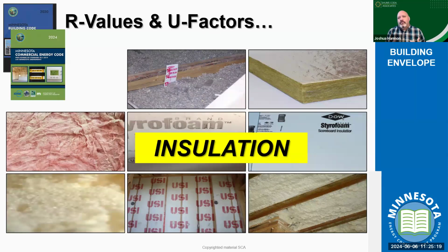If I don't properly designate, and all I see is that I'm putting in a spray foam at R20, and it's not clearly defined in my construction drawings, construction documents, that the system is also providing the air barrier, and the contractor replaces it with an R20 batt insulation, then I'm not going to be able to make sure that project is successful the same way.